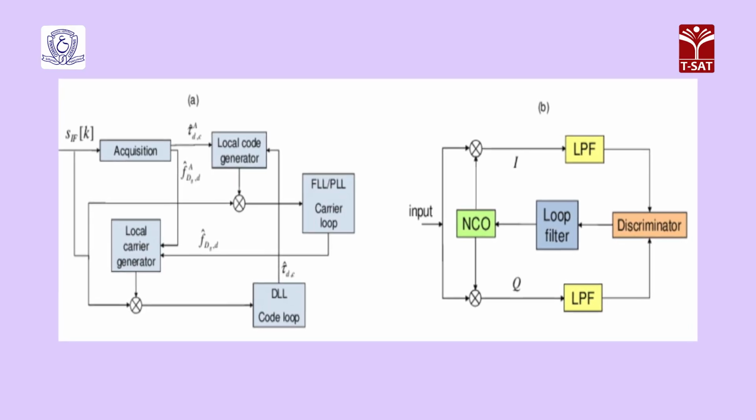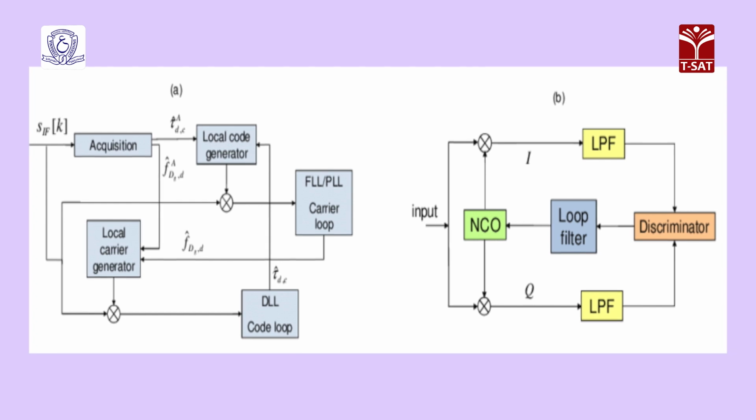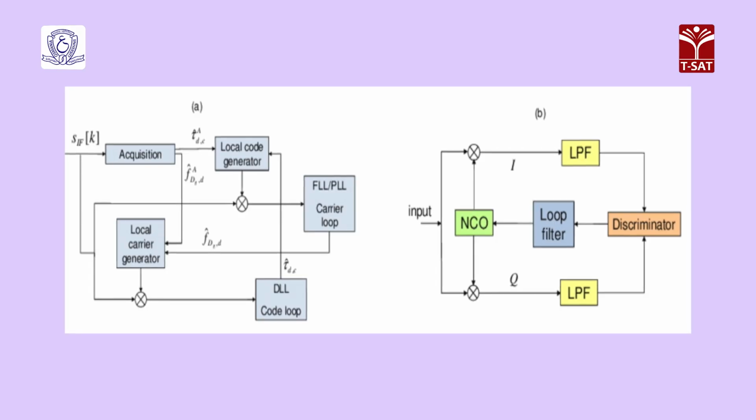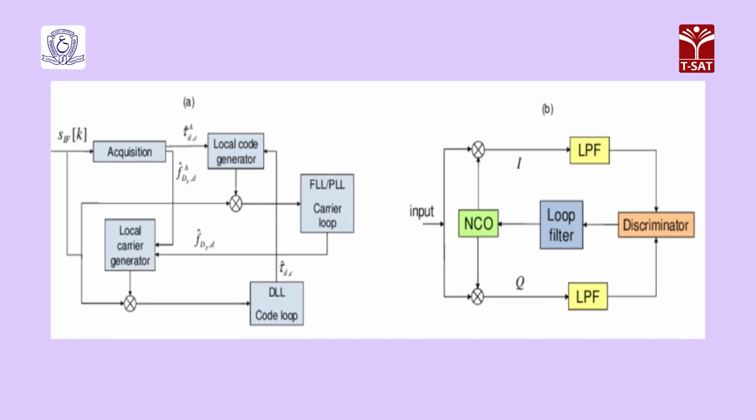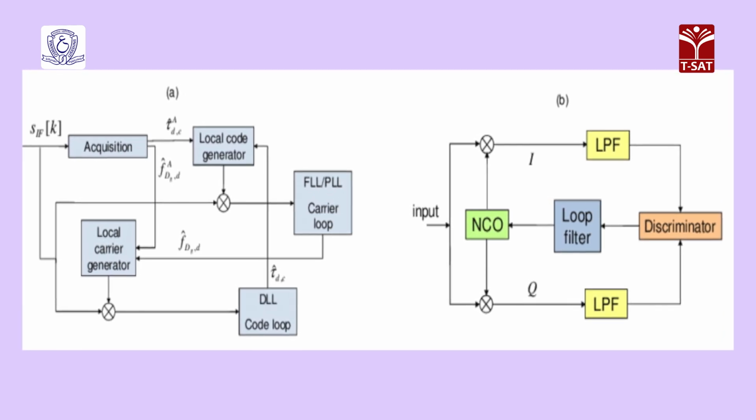Receiver noise and resolution. Measurement errors are also induced by the receiver tracking loops. In terms of the DLL, dominant sources of pseudo range measurement error, excluding multipath, are thermal noise, jitter, and the effect of interference. Receiver noise and resolution errors affect carrier phase measurements made by a PLL.